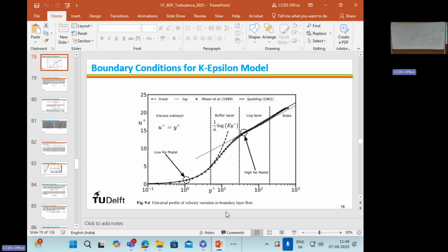This is another way of non-dimensionalizing it, because to solve for y plus, we need an additional non-linear equation in terms of the product of linear and logarithmic values, which needs the Newton-Raphson method with some guess value. You go on finding the things, right? That's why, to avoid those things, you now solve for y star, u star.